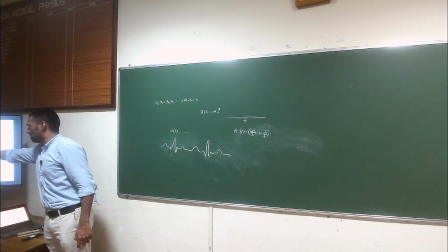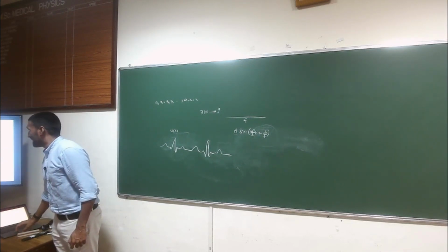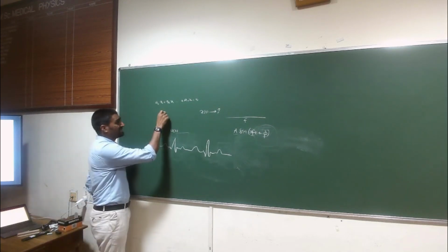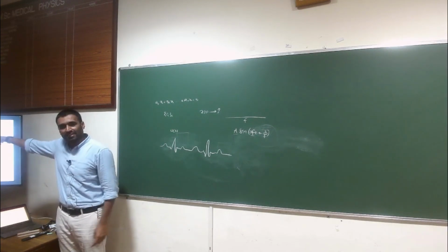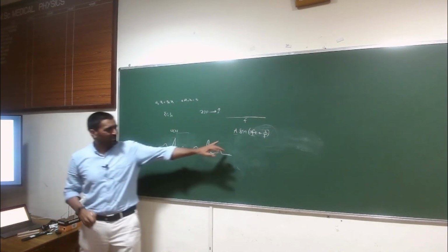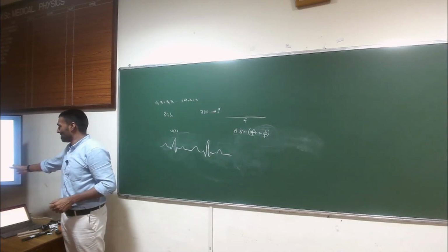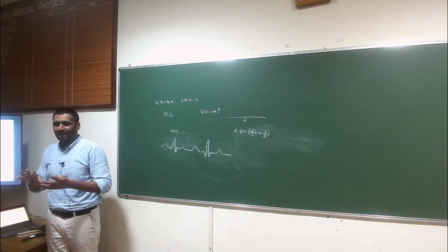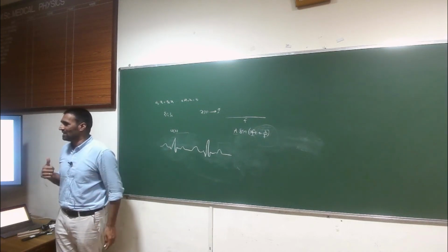These phi i's are often called basis functions. Another way to think about this is, if I can successfully represent x of t like this, then all I have to tell you are the numbers ci. If I give you these numbers, then you can perfectly reconstruct x of t, very similar to something like this. Computing the ci's and manipulating them will help you change the signal in the ways you want, to be able to extract useful information.